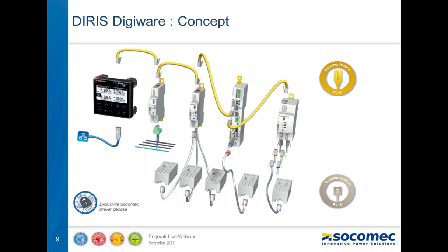All these modules are linked through a specific bus, the yellow cable that you see. And also the main innovation is about the current sensor. The current sensor is already a main point for the installation, and in a substation you can't cut the current. You need to operate in a live working environment, and all our system is really developed for that, to have a safe and secure installation very quickly, with all cables now in RJ12 or RJ45. It is a very plug and play system.